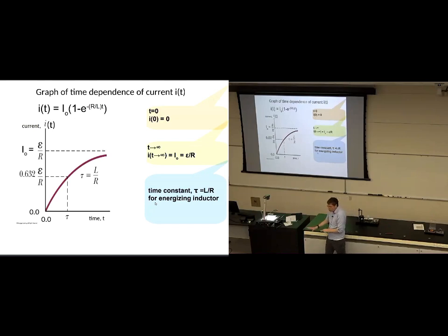We said we closed the switch at time 0, but because of self-inductance, because of induced EMFs and induced currents, we don't think the current will immediately ramp up to the full current given by Ohm's law for the resistance of the resistor in the circuit. It takes some time. Here you see that evolution. Zero current initially. I0 is the final current of the fully energized circuit.